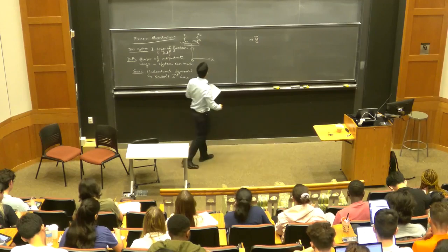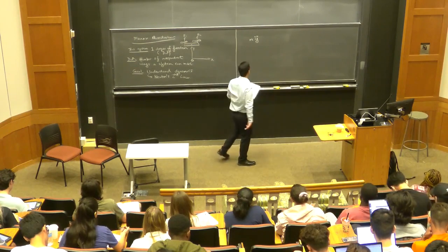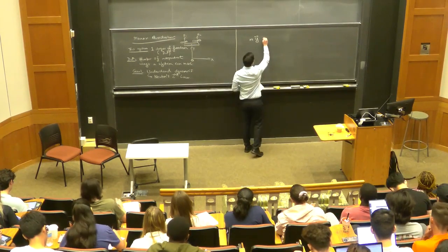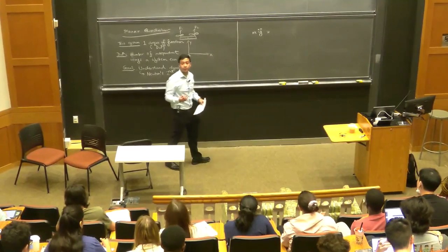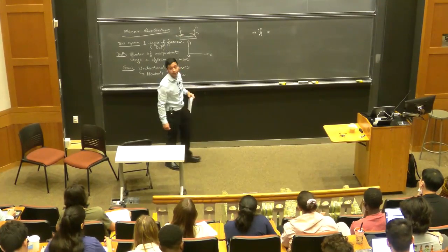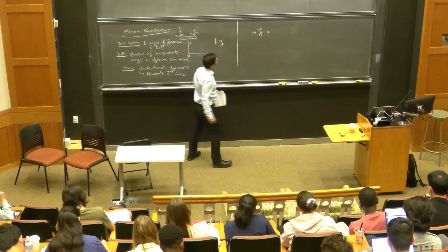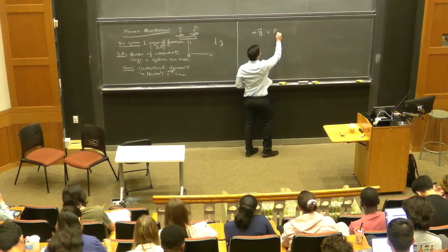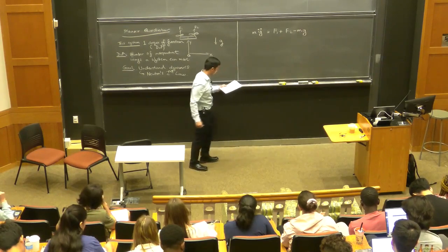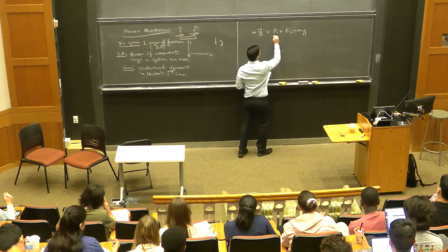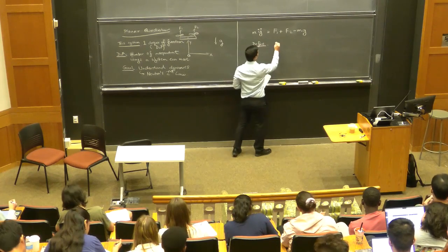Let's say the mass of the drone is little m. Y double dot is the acceleration of the drone. Again, everything is just in the y direction. That equals the total forces acting on the system. There are 3 forces total: F1 and F2, the thrust forces from the propellers, and also the force of gravity. Let's say we have gravity pointing downwards. So we can write m times y double dot equals F1 plus F2 minus the force of gravity. Okay. We're just going to define a quantity that we'll call U1.